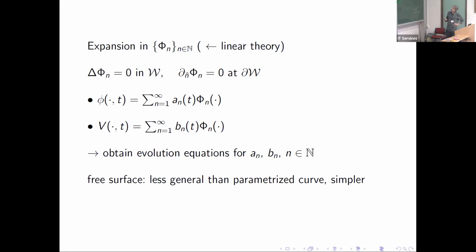And then we have some other idea that comes again from the linear theory, that we are now thinking of in a somewhat more practical way: the two dynamical quantities, the hydrodynamic potential and this auxiliary vector field, can be expanded in these harmonic functions that come from the linear theory. So we have some kind of expansion, and the goal is to find the evolution of these two quantities, or equivalently to find some equation for the evolution of the coefficients. So we are now thinking in terms of some kind of spectral description of the dynamical equations.